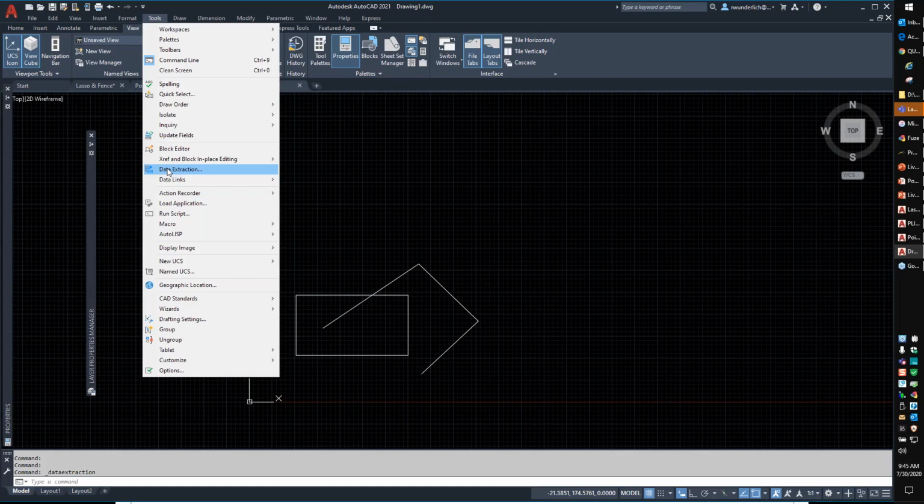Sometimes as well, especially with the new 2021, if you double click to modify an OLE object, you modify it and you put it back, it may shift and/or rescale itself. And then once you've rescaled it back and moved it back, it generally is okay.